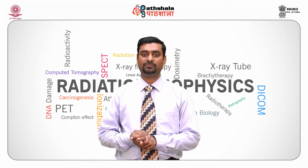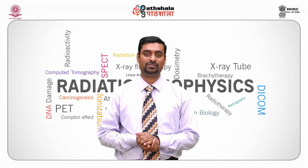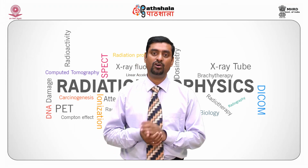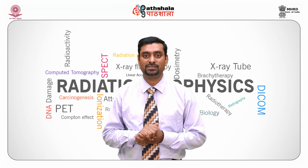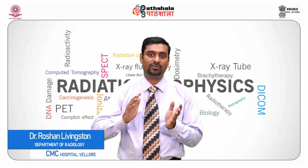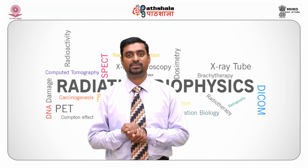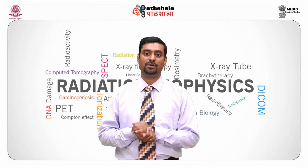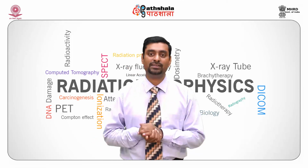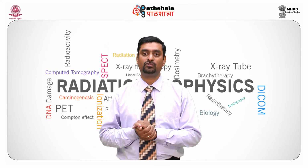In an indirect method, CCD cameras are used as well as amorphous silicon. In both these technologies, a scintillation material, either cesium iodide or gadolinium oxysulfide, is used. The work of the scintillation material is to convert X-rays to light. Now we need to convert the light into electrons. We use optic tapers, and the light falls on a CCD camera, or we also have an amorphous silicon photodiode array and a TFT, which will convert the light into an image so that it can be viewed on monitors.